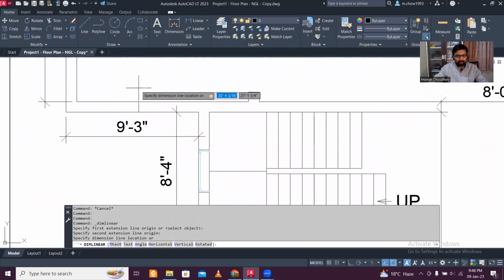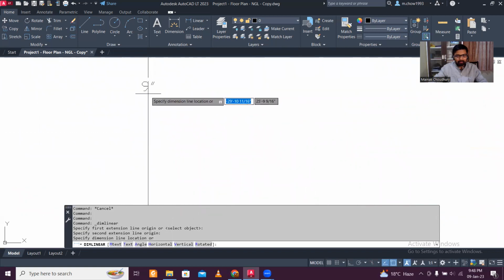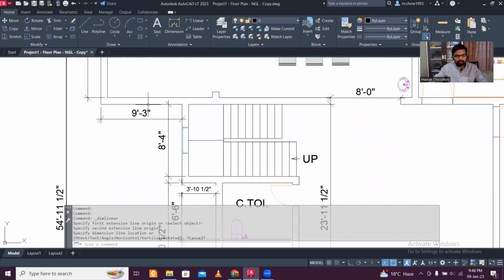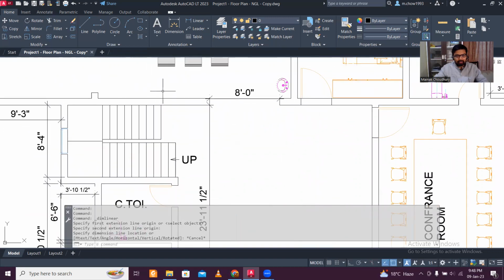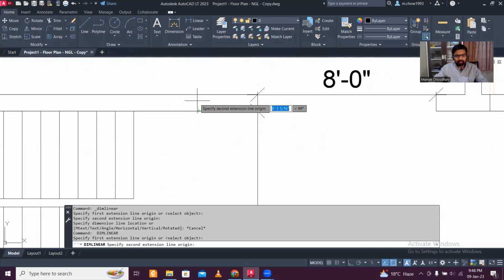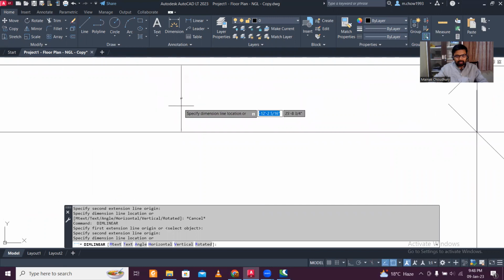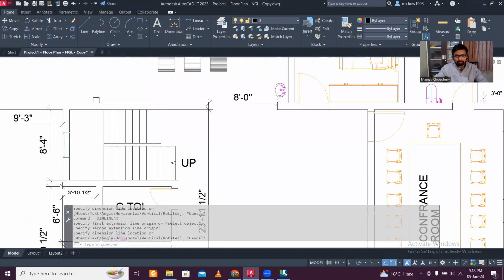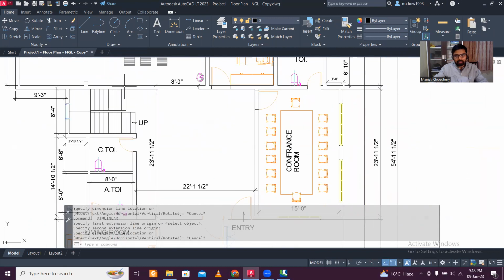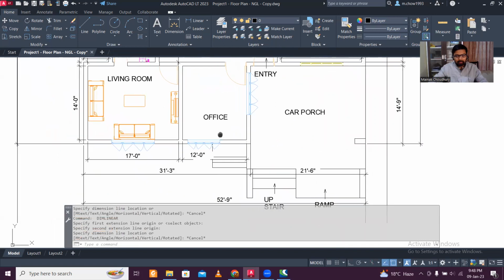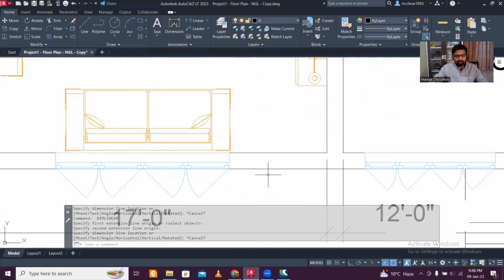Okay, what are the dimensions? 9-inch wall. Okay, interesting. 9-inch wall here. It depends on the area, because I think this construction is in Bihar. So 9-inch bricks are available there, or rather 8-inch bricks are available there, and 1 inch maybe for plaster. So that's why it depends. Like in our state, along with plaster it becomes 10 inch. So it depends on area to area what the size is.